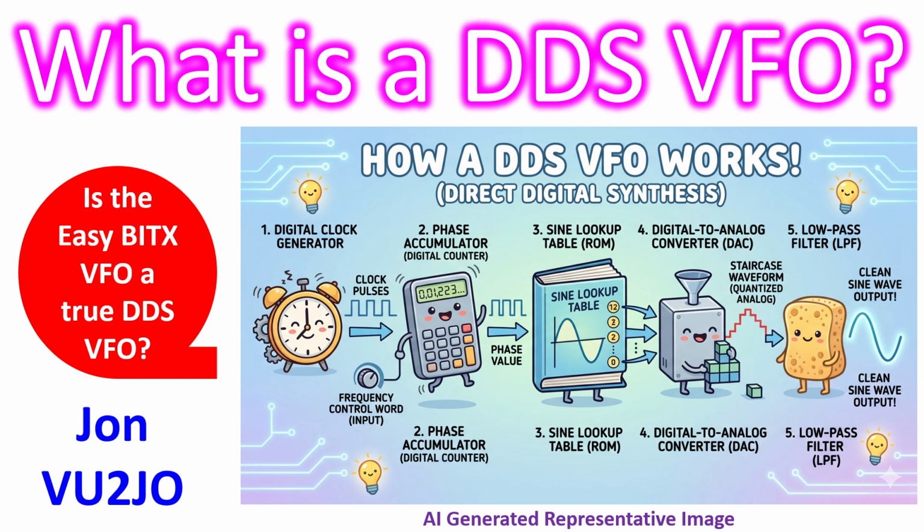A DDS VFO stands for Direct Digital Synthesis Variable Frequency Oscillator. It is an electronic system used in radio transceivers to generate a highly stable, adjustable radio frequency signal using digital signal processing rather than traditional analog tuned circuits like coils and capacitors. In modern homebrew and commercial amateur radio rigs, it serves as the tuning dial generating the local oscillator signal required for mixing down received signals or mixing up transmitted signals.